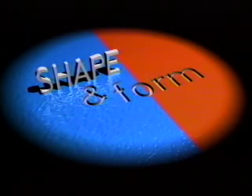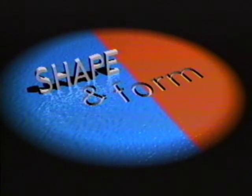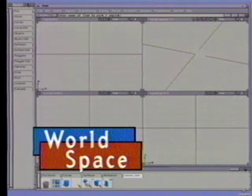In Alias, you will build models by giving shape and form to objects in a virtual 3D space. Modeling involves building objects out of primitives, curves and surfaces, then scaling, rotating, and moving these objects into realistic shapes. Starting with basic primitives, you'll be learning how to place and position objects in 3D space, then how to draw curves and create surfaces. Version 6 users should note that in this section they will learn about the new information window as well as new methods of picking objects when using the Xform tools.